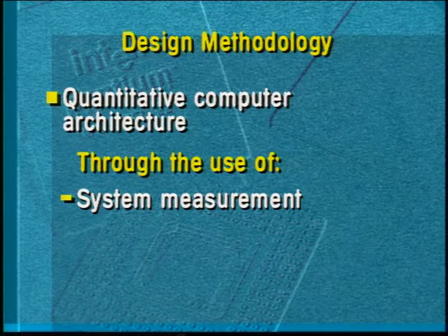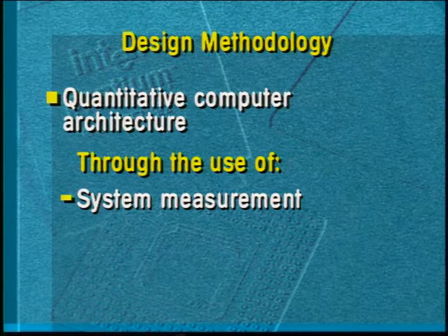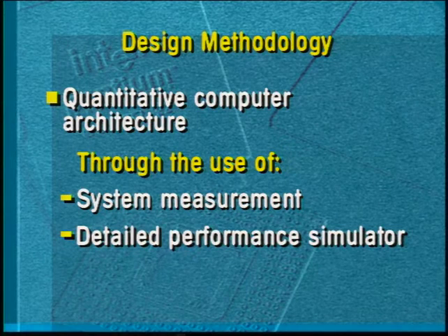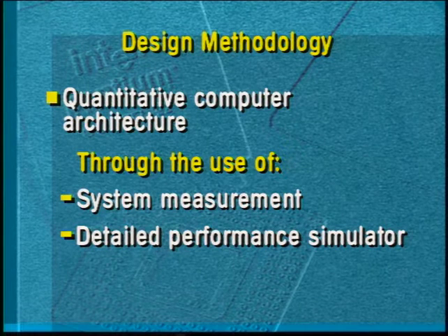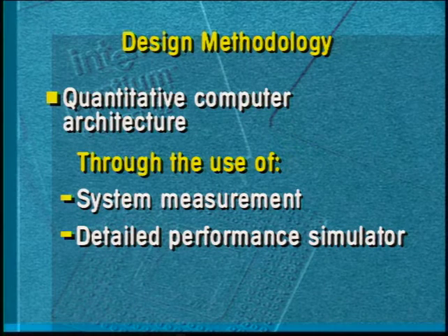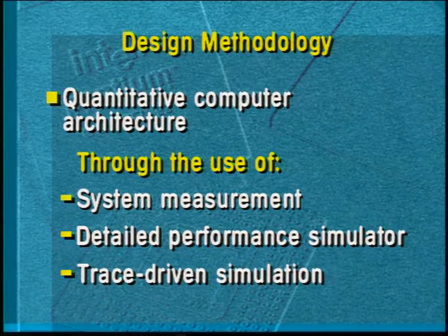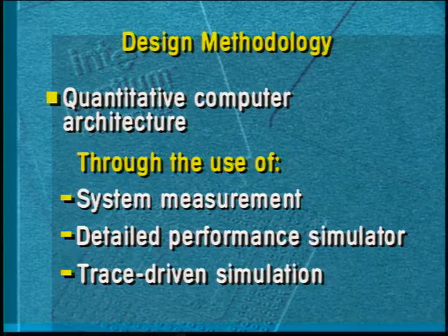One technique we used was system measurement, where we could measure programs executing on 386 and 486 systems and project forward to the Pentium processor from these system measurements. At a more detailed level, we developed a very flexible and detailed performance simulator that would very accurately estimate the performance of different software running on the Pentium processor, long before it was realized in silicon. In order to drive the simulator, we collected a number of traces across a broad spectrum of application areas and used these traces to drive the performance simulator.